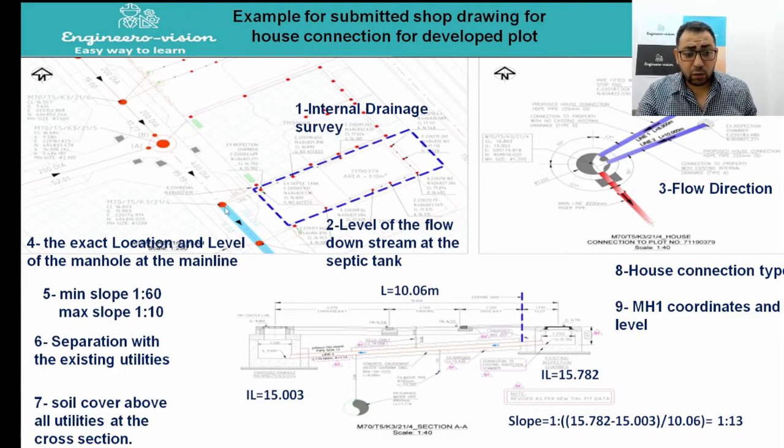Is this location of the manhole the final location as per the IFC drawing? No. The final location of this manhole will be determined based on the direction of the lateral connection to this manhole.